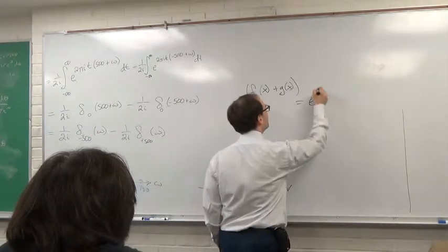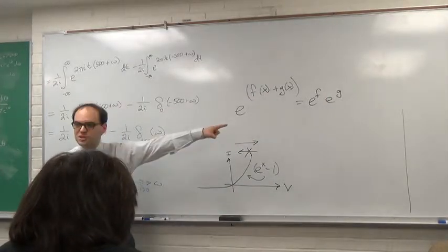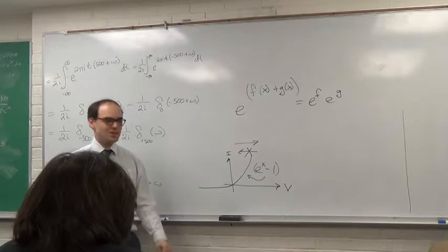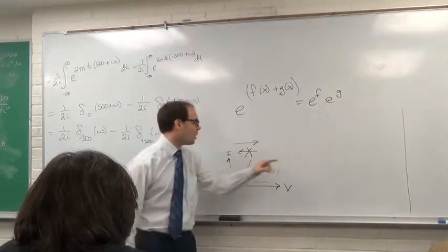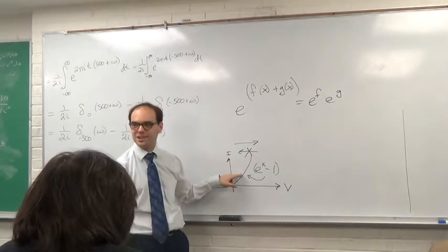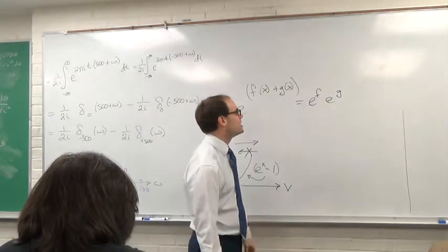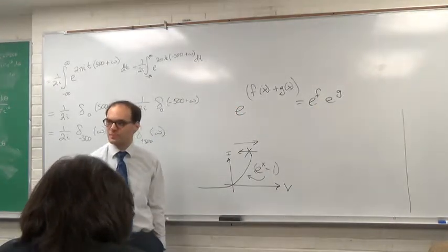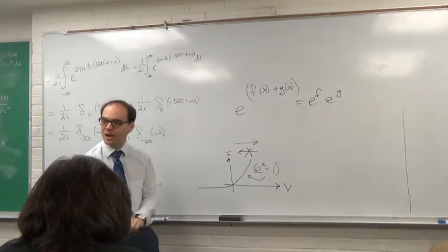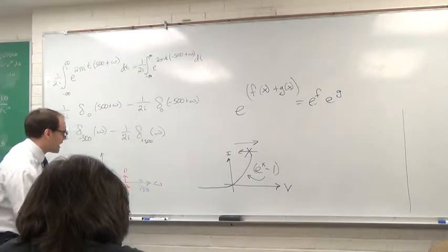Yeah, e to the f times e to the g. That's what you get. So in fact you do product the functions. Now you product the exponential versions of these functions, but you make f and g kind of small, so the linearization is about right here. So you end up with a linear approximation of f, a linear approximation of g, or at least slightly distorted versions, and you in fact do product them together nicely. So that's how people build these multipliers. They call them mixers. So anyway, that's a very practical application of this.